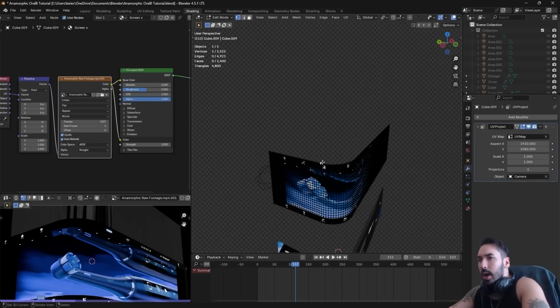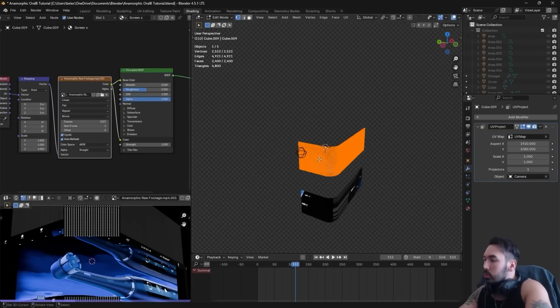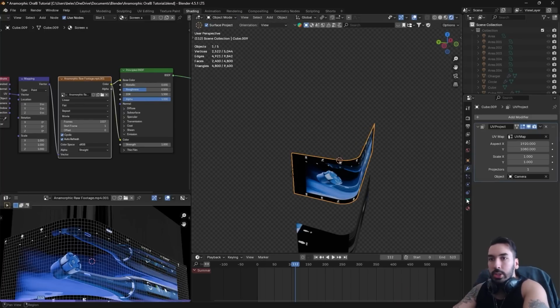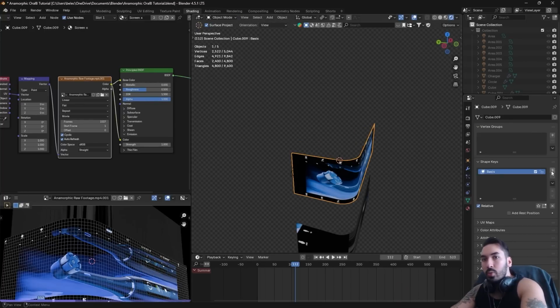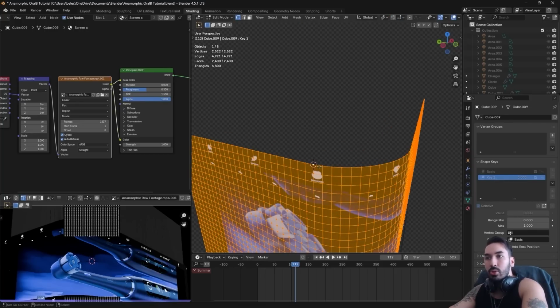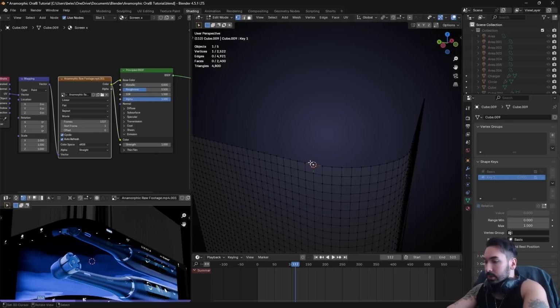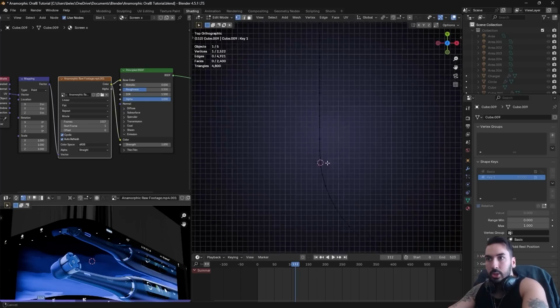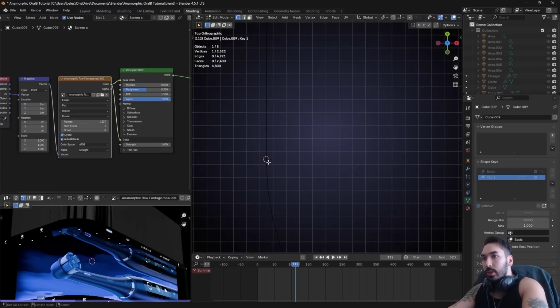on another screen. Now I don't know if there's an easy way to turn this into a flat surface. I'm just going to do it manually, and here's how you do it manually. We're going to go to this object data properties. You're going to click on shape keys once, then click on this plus again, and now with key 1 selected here, you're going to place your 3D cursor onto the first segment of this bevel which we created in the beginning. So in this case, if we zoom in, that's going to be this vertex right here for me, and